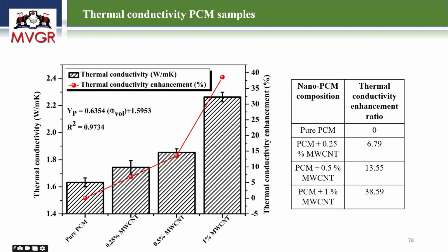And coming to the thermal conductivity, that is why we are mixing these multi-wall carbon nanotubes. The main agenda is to increase the thermal conductivity, so that's what we need to check. Here I was conducting the thermal conductivity test. Here the pure PCM thermal conductivity was around 1.62 watt per meter Kelvin.